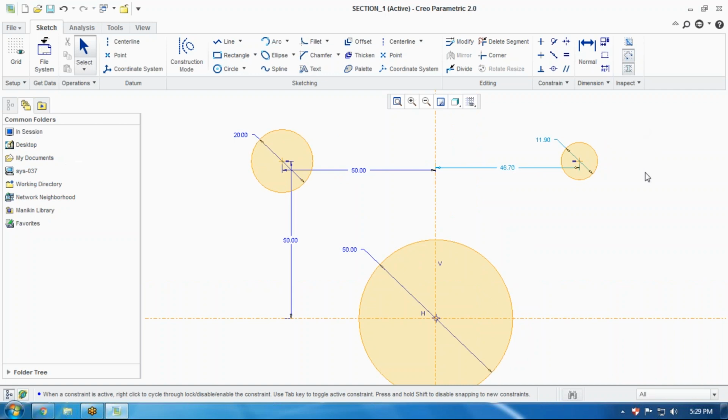So do one thing here. If you want to make the same relationship between them, means equalization, go for the constraint bar here. This is the constraint bar, and it shows you the equal relationship. Go for this, select 1, then the second, and they both will be the same. R1 shows the same diameter or radius, so I'm double clicking on this.